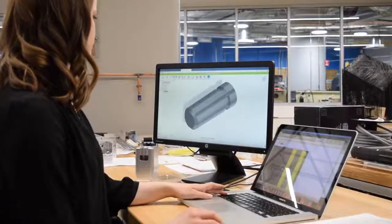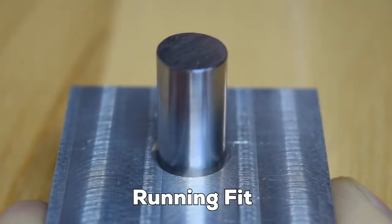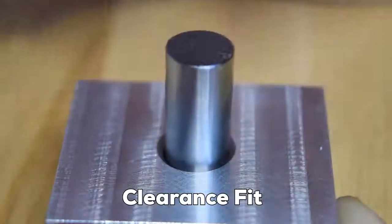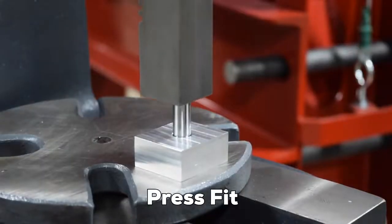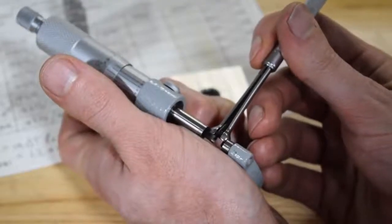So how tight of a tolerance do you need? Tolerances typically come into play when designing fits. In some cases, you might want components to slip together easily, but not have a lot of perceptible play. In other cases, lots of relative movement is okay. You might even need to have two components come together permanently and not come apart. These different cases are called fits.